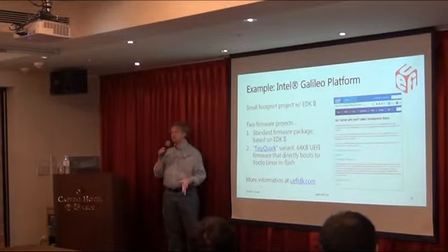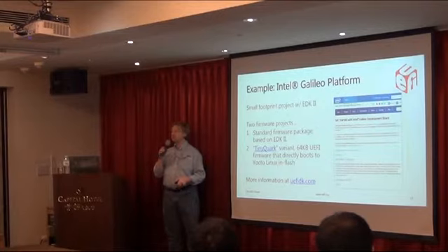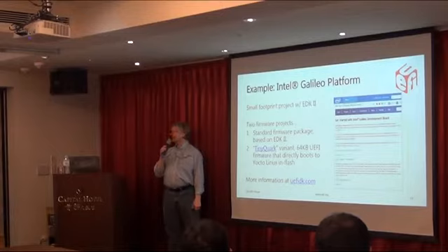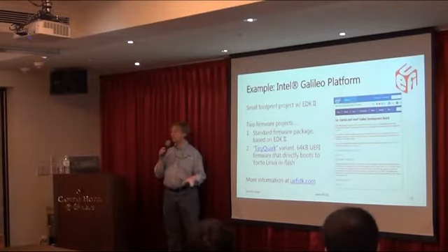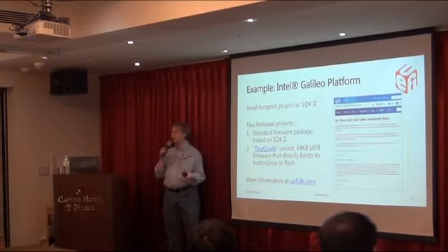Everybody, and if you look at all the security attacks people talk about, they say UEFI is too big. Now what they mean is if you implement everything in the spec, UEFI is too big. But nobody implements everything in the spec on a single system. So the Quark is a nice chipset because it has no video, very low speed, has very few bus interfaces. It uses total in its EDK2 project 11 modules, 11 packages total. 3 of those are Intel and the other 8 are open source.